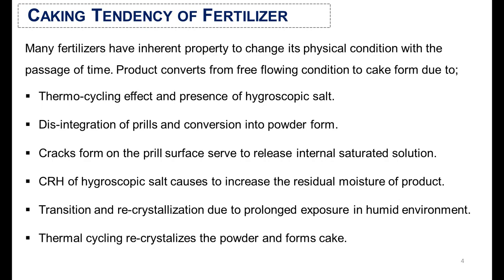Actually, the prills disintegrate and convert into powder form, and cracks appear on the prill surface, releasing the internal saturated solutions, while the hygroscopic salt increases the residual moisture of the fertilizer product. So transition and recrystallization, exposure of the fertilizer in a humid environment converts the free flowing fertilizer into cake form.